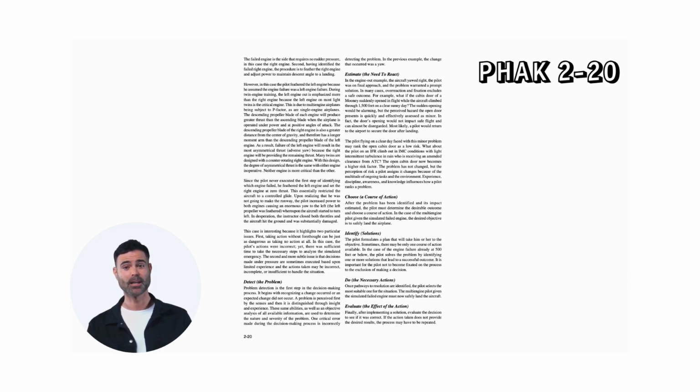The sudden opening would be alarming, but the perceived hazard the open door presents is quickly and effectively assessed as minor. In fact, the door's opening would not impact safe flight and can almost be disregarded. Most likely, a pilot would return to the airport to secure the door after landing. The pilot flying on a clear day faced with this minor problem may rank the open cabin door as a low risk.